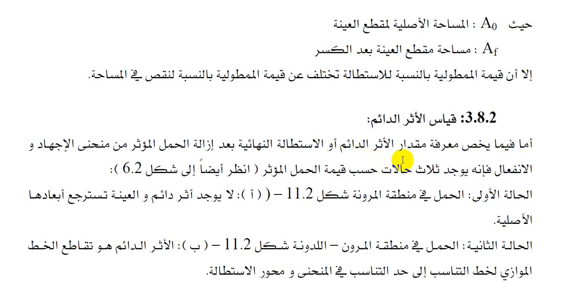Whereas for computing the permanent set magnitude, or the final elongation after the effective load, from the stress-strain curve, there are actually three major cases according to the effective load value. You can also regard figure 6.2, as you can see illustrated right at case 1.